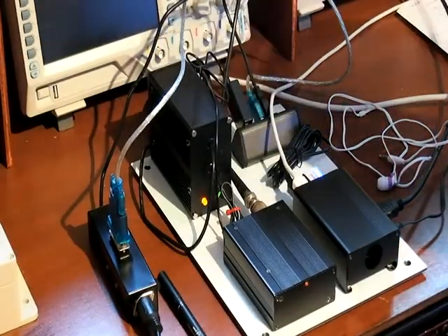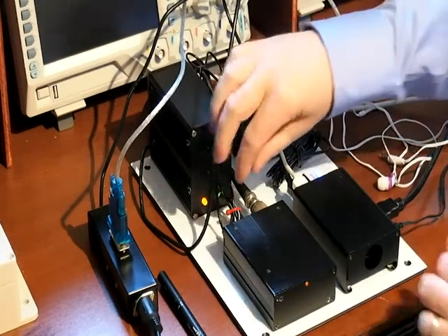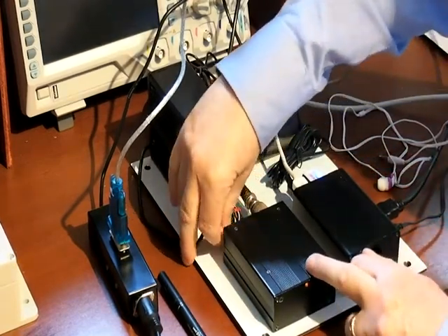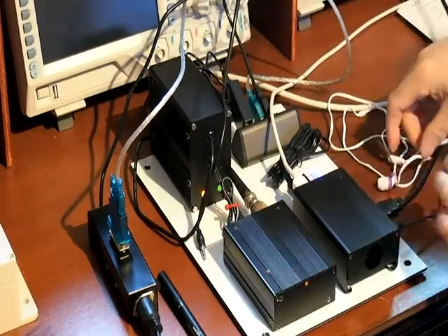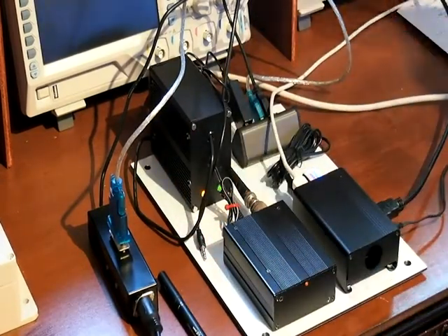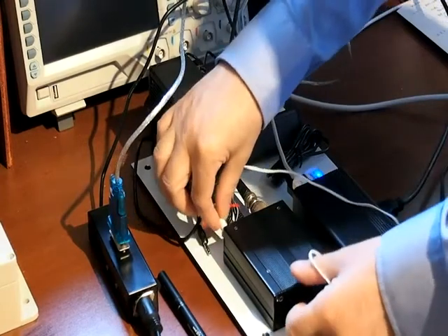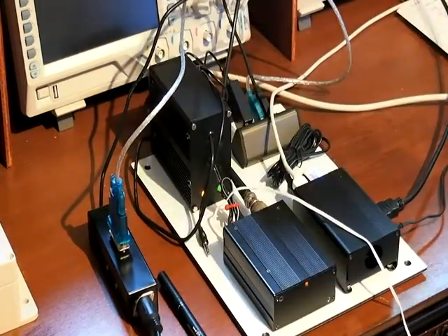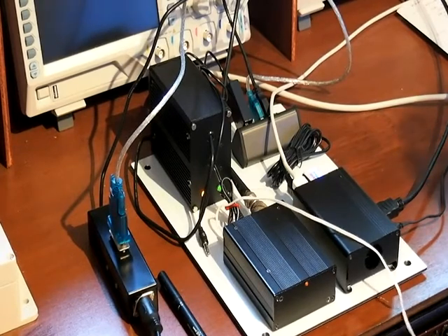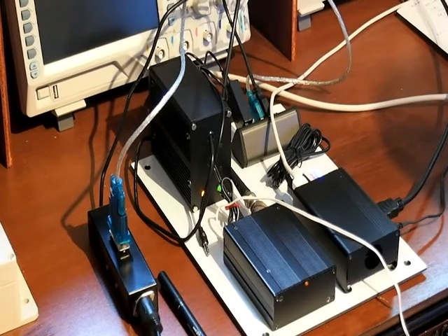So to check the hardware of the Whisper receiver, I'm going to unplug the 3.5mm jack plug from the receiver box here and plug in a simple earphone instead and have a listen. The signal level is very low into the earpiece.